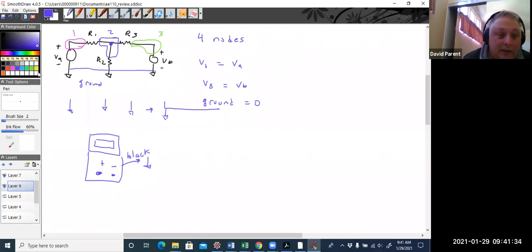In mesh analysis, we showed a voltage drop across the resistor, and that meant the voltmeter's positive end is here and the negative end is there. Positive, negative, positive, negative, positive, negative, all right? But that's the key thing to remember, is that really potential, you have to have 2 points to measure it. It's a height. It's from one place to the other.